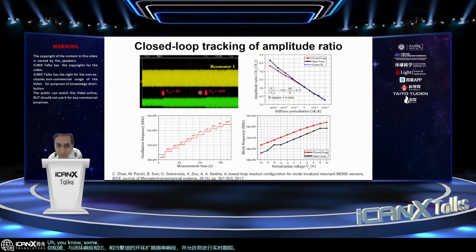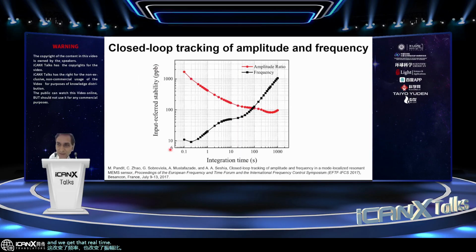any changes in measurand here, dialed in by changing the voltages to tune the electrostatic spring on one of the resonators relative to the other, and that changes the frequency, that changes also the amplitude ratio, and we get that real-time tracking.